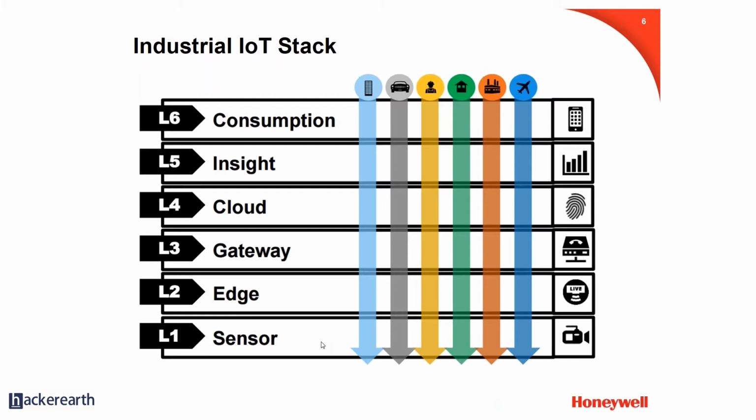And in many cases, the line between sensors, edge, and gateway can get blurred, especially when the devices are more powerful. If you look at some of the development kits, I'll come to it in the later slides, they have a lot of these features baked in, and they probably still need a wireless access point or something. But if you have a cellular radio, maybe you don't even need that, and you can just bypass the gateway and directly get onto the cloud.